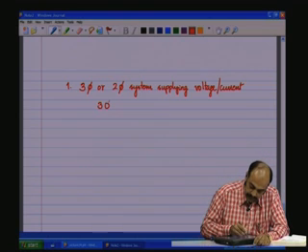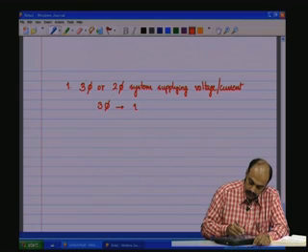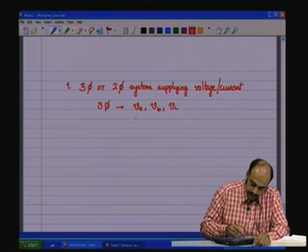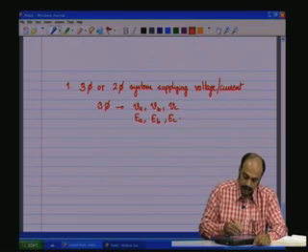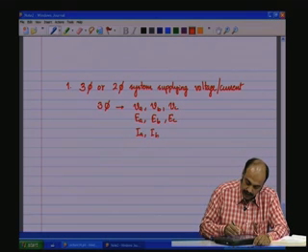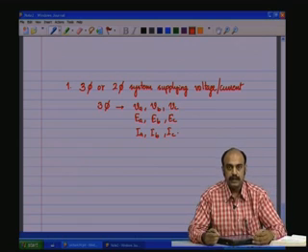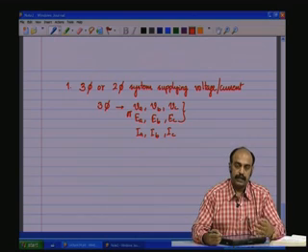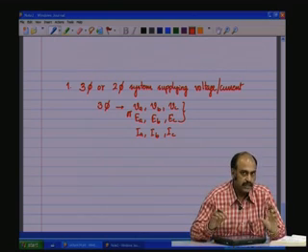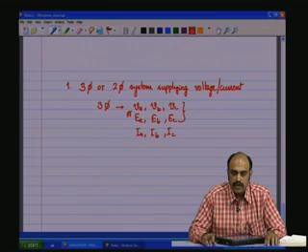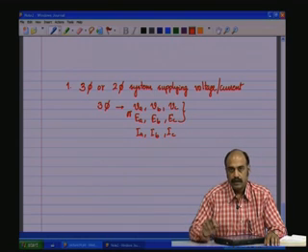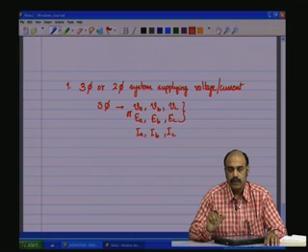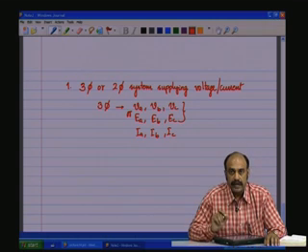In the case of a three-phase system, we have VA, VB, VC, or we will say EA, EB, EC, and then you have IA, IB and IC. These are the three line voltages and the line currents. Now, all are having the same magnitude and are displaced 120 degrees apart, and this displacement of 120 degrees is in the time axis.